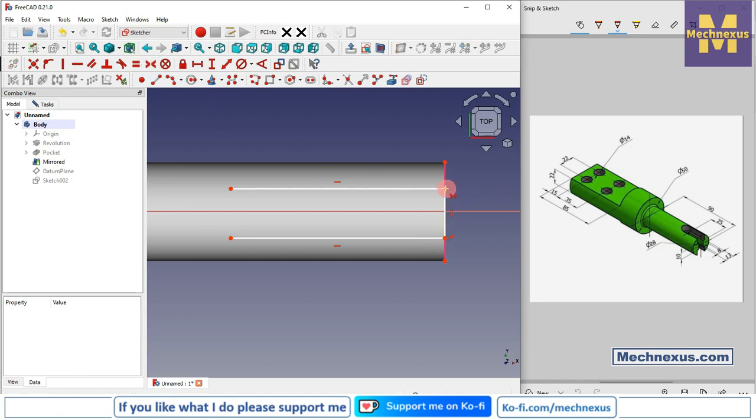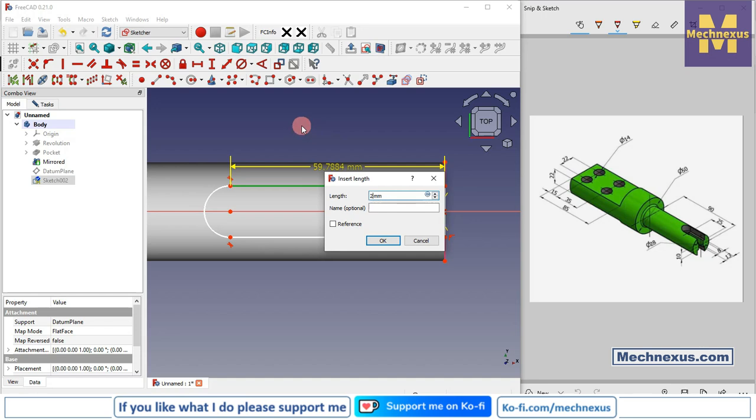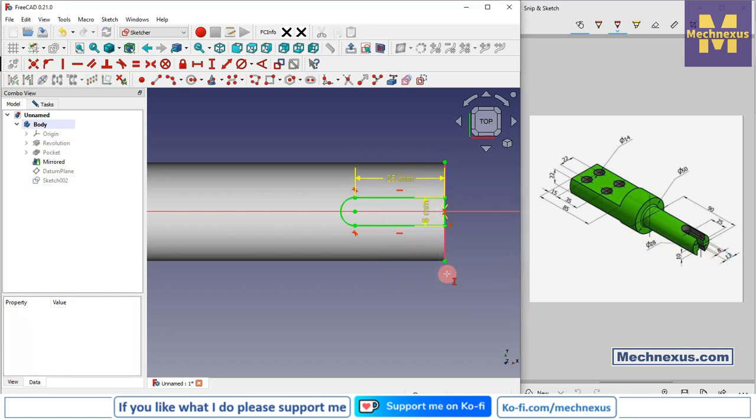So select the symmetricity constraint, select this point and this axis, and here I will create a 3-point arc and provide the tangency. Now I will select a horizontal dimension and provide this dimension 25, and select the vertical dimension and provide this value of 8 mm here and click on OK.